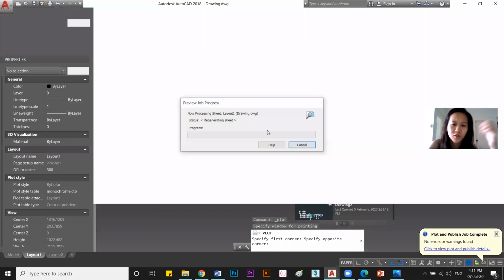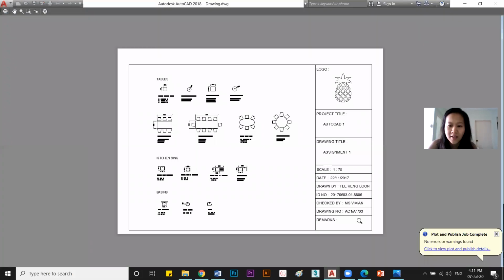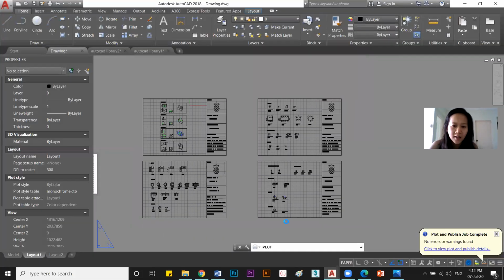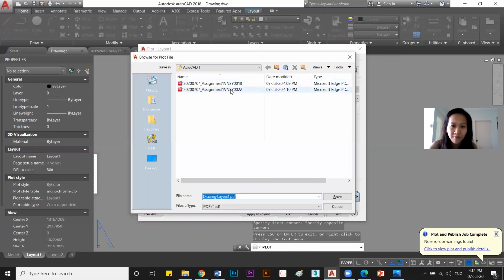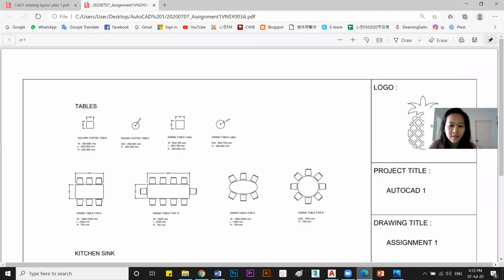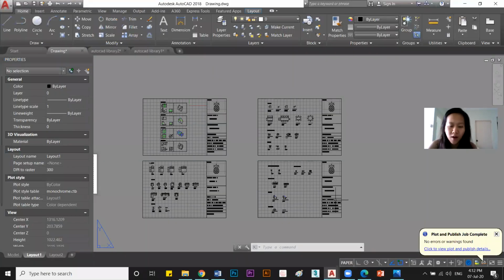Then you go to preview, check whether this is the third one or not. Yes, you can see the drawing number here, 03. You can zoom in and check. Once it's done, close. Then you just okay and save as 3A. Very, very fast, right? Then just save. Ta-da!